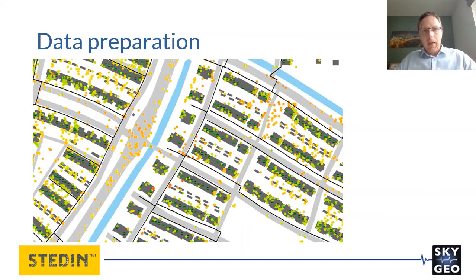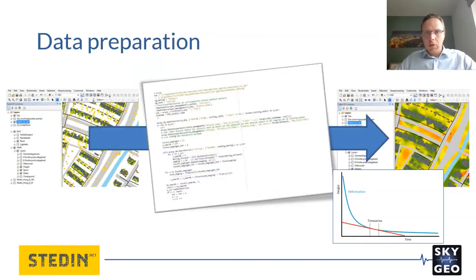Thank you, Martijn. The data we receive from SkyGeo we plot on a map together with our asset data. In this map, the black lines represent our mains, and you can see that the mains do not intersect in all locations with a measurement. This is something we would like to have to be able to predict the probability of a failure on a main and on a service line.